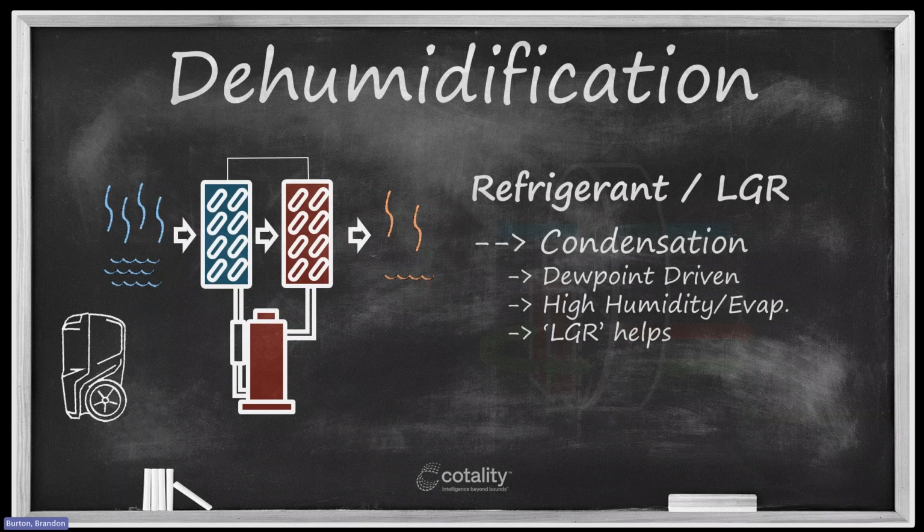What an LGR does is it then folds that sponge in half and squeezes it again. There's a second cooling mechanism that happens inside of an LGR, and I'm not going to run through the technical details of that today, but in essence, that's what's happening. The low-grain refrigerant leverages some efficiencies that already exist in that refrigeration system to cool the air not once, but twice. So that I get more water out of that sponge. So I produce a much drier air on the exhaust. But even with LGR, you're still limited by the refrigeration limitations, right?